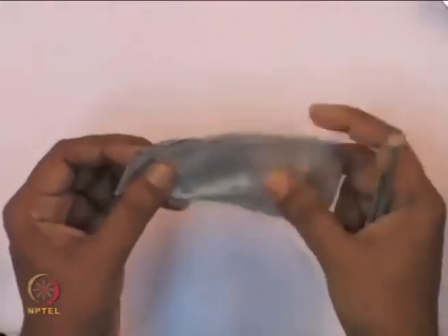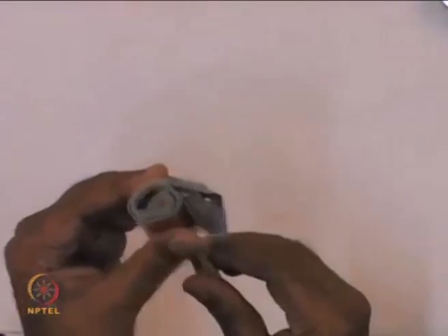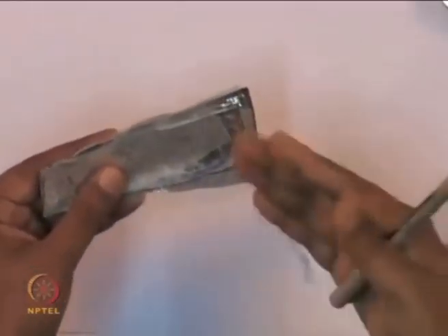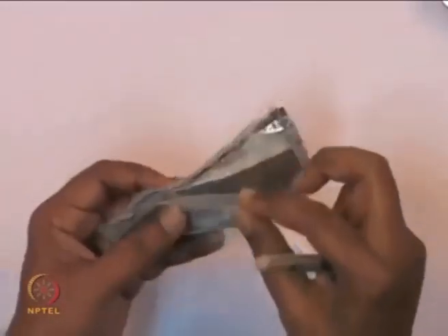Now, this multi-layer insulation is wrapped around, for example, this cold finger. I will wrap this multi-layer insulation in a very typical manner, and what is most important is how many layers there are. One may have 10 layers or 20 layers or 30 layers, and that also one has to optimize depending on the temperature, the heat in-leak, and also the vacuum around.